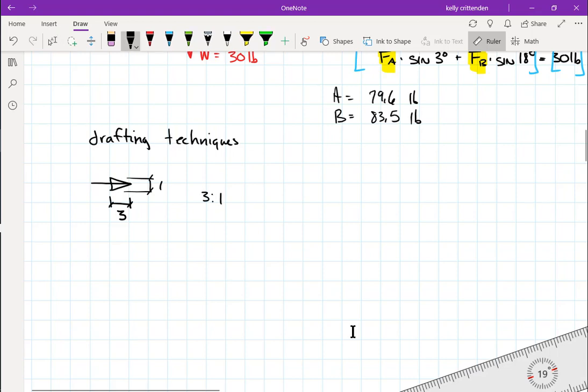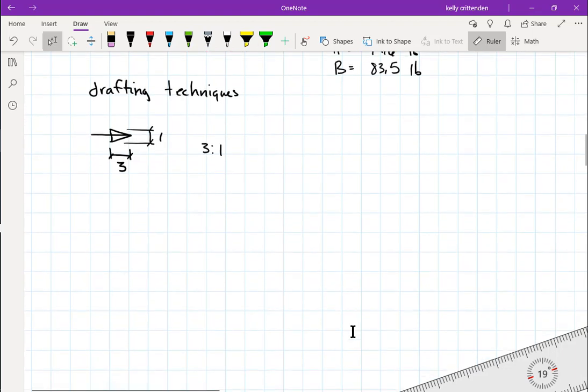If you get them roughly that ratio, you don't have to go measure any of this stuff. And if you're doing SolidWorks, then they just spit them out that way. But it gives you a consistency, so you're not confused whether this is a little extra dot on your page or the arrowhead on the end of a leader line or on a dimension line. So that one's not super important, but if you were a drafts person back in the day, you would have learned that the ratio of arrowhead length to width is 3 to 1.